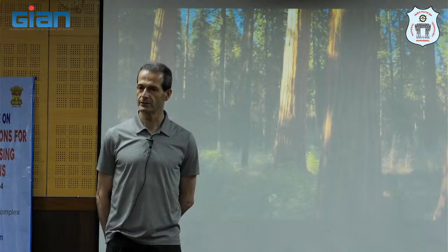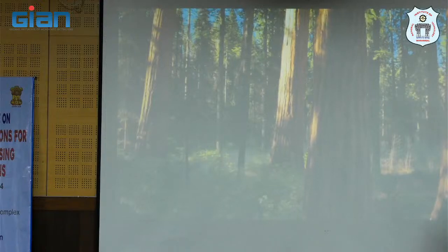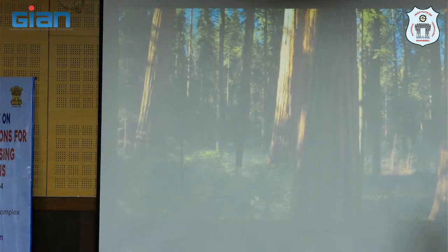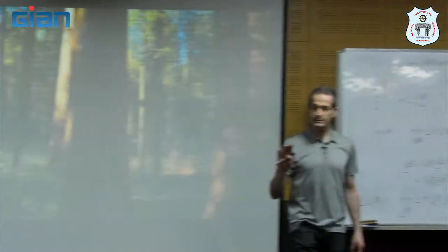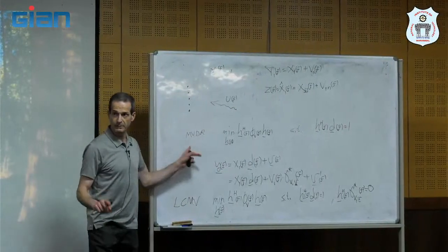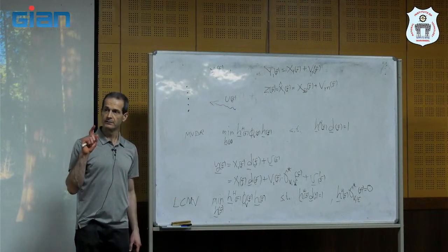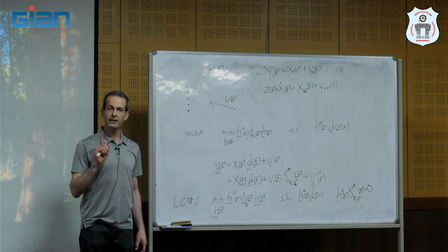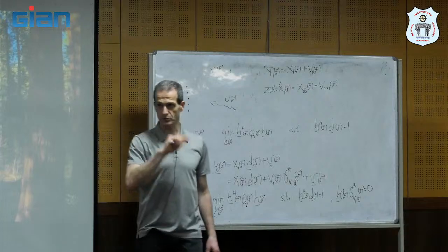Under which conditions? Okay. So when we compare MVDR and LCMV, if the objective is maximum output SNR, or equivalently, if the objective is to reduce the power of noise, then MVDR will always be better. So LCMV is better when we talk about a different objective. The objective is not to reduce more power of the noise. Different objective.